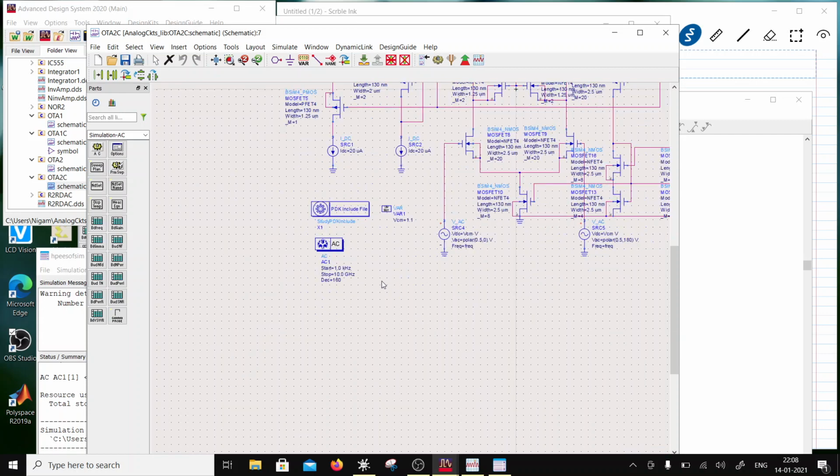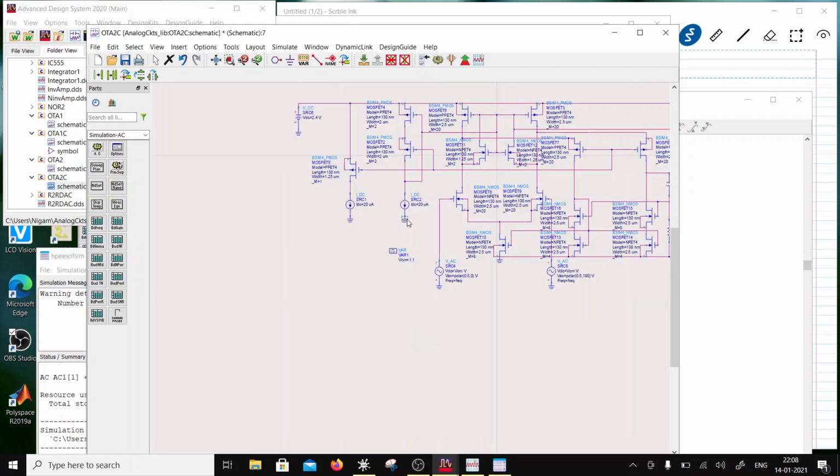To make this component I will just throw out these. Okay, and I will leave the common mode. So in this case I am going to just have same grounds, just like I did for the previous one. So this is one ground over here, and these are my inputs. So this is a non-inverting input and this one is a inverting input, right? So I am going to just make sure my grounds are proper.